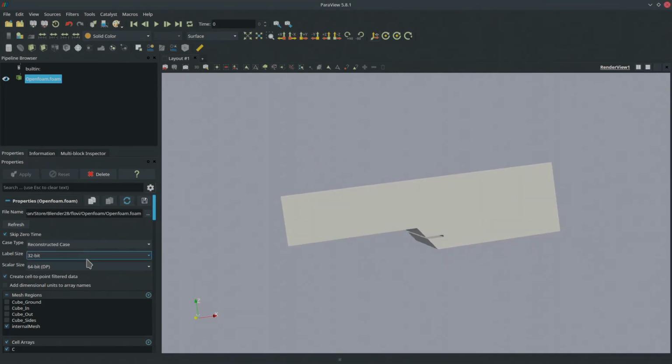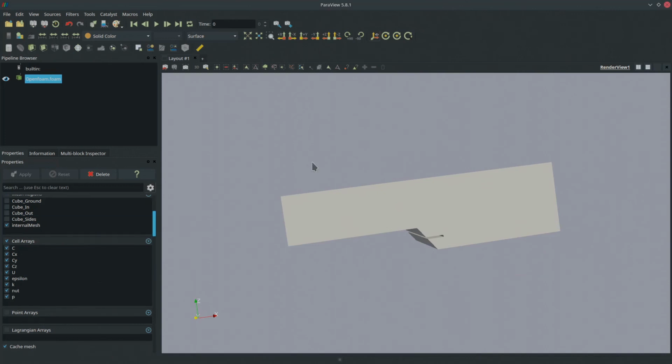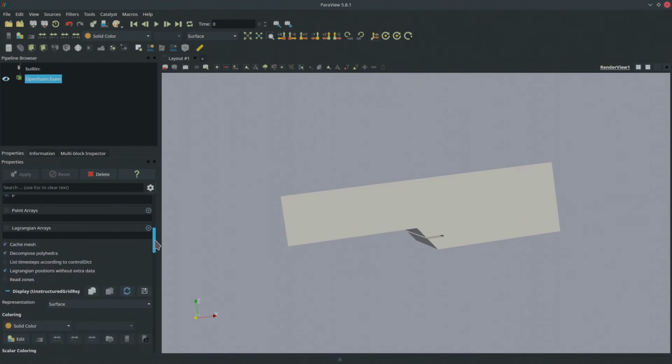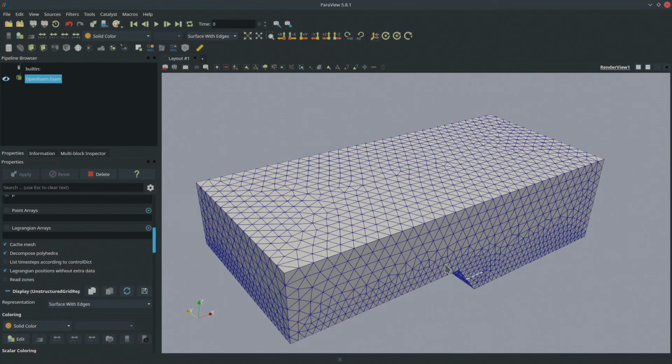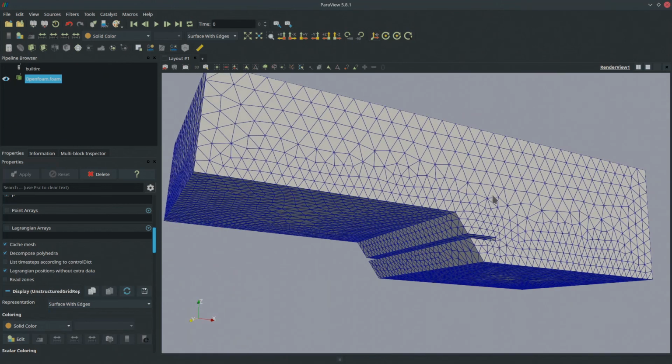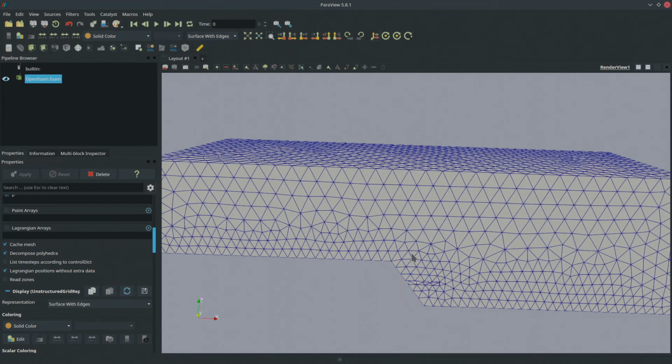hopefully I can now see. Now this is ParaView, and I'm not going to go into the details of how to use ParaView, but it's really good at visualizing CFD results, and currently there's no way within the V Suite to visualize CFD results. I just use ParaView. But there you can see the tetrahedral mesh. So this is the mesh produced by NetGen, and if polygonal is turned on, then we convert that into a polygonal mesh.